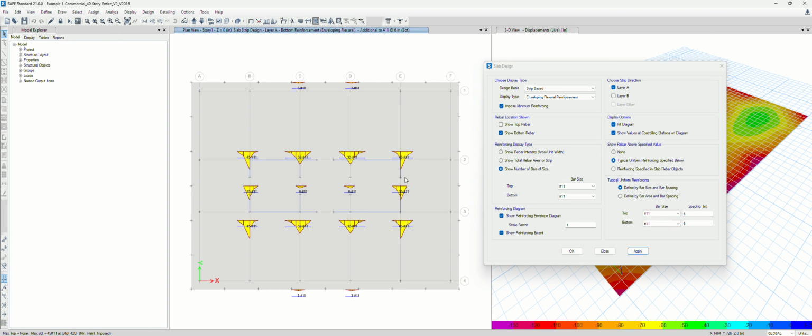Now still we have a lot of additional bar to deal with somehow, and that makes sense, because the concrete wall carries a lot of gravity and lateral load, so typically you'll see more heavy bending moment and shear under the wall. So at the end, we may end up with multiple layers of rebar, because you think this is almost, what, 96 inch mat. It's almost one floor thick mat, right? Probably end up with a couple of layers, right?